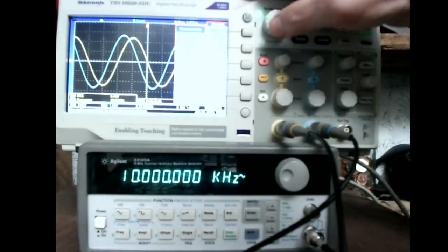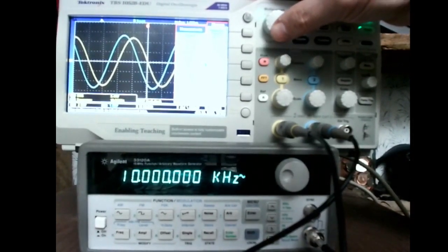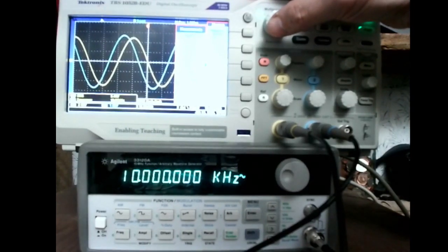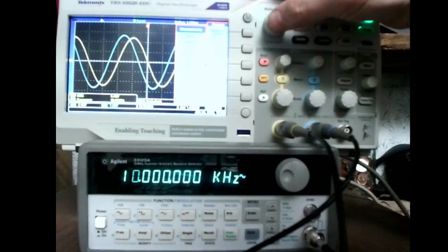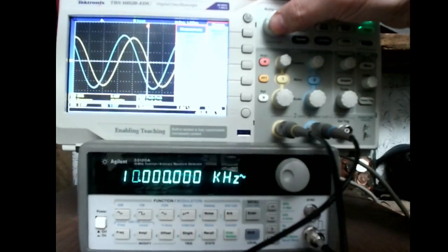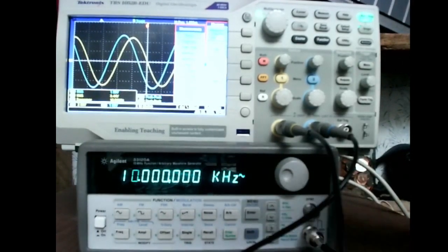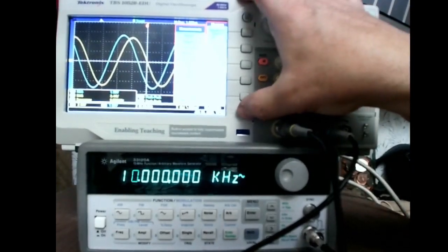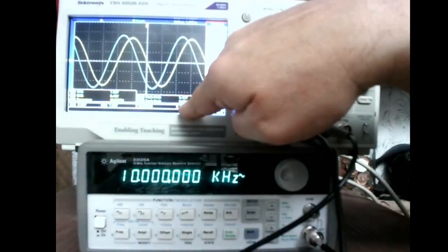Similarly, you can go over to channel 2. Now, there's no sense in showing the frequency for channel 2 since the frequency for channel 2 is just being driven by channel 1, so it's going to be the same frequency. But we might want to see the peak-to-peak for channel 2, and we might want to see the RMS for channel 2. And so we can add those all to the screen here, so it'll actually read what those values are.